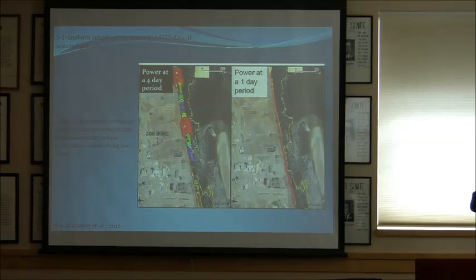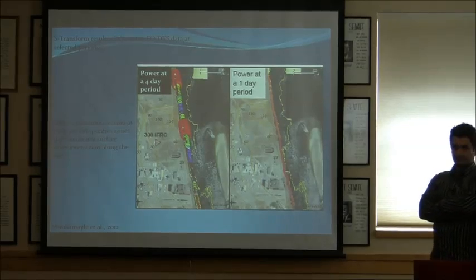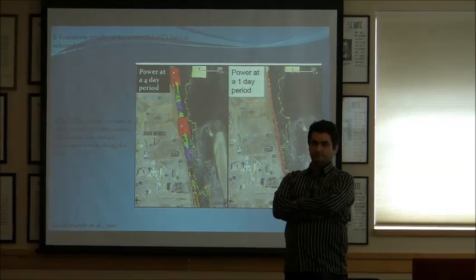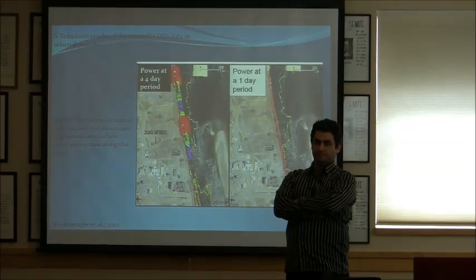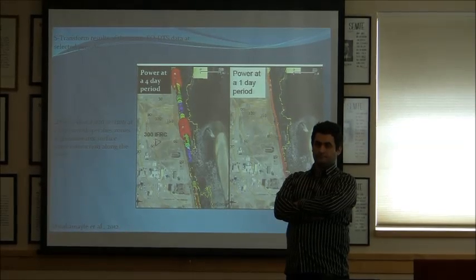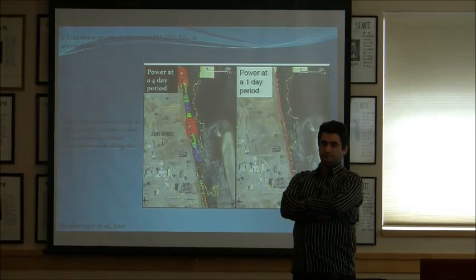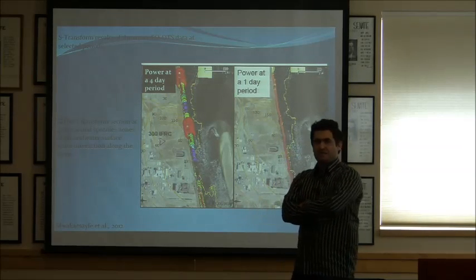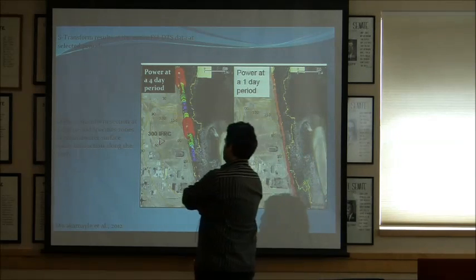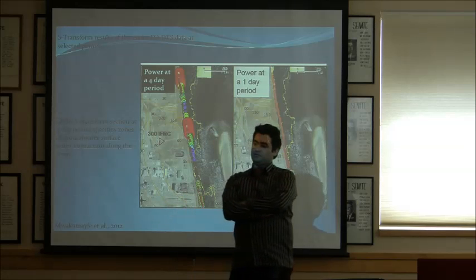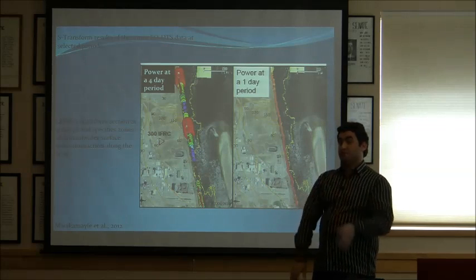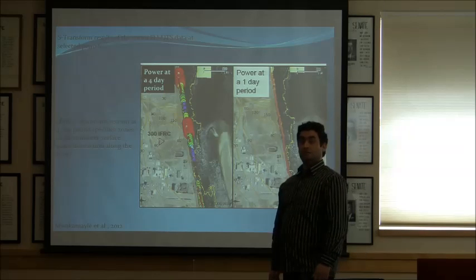I do have a question from earlier, when you were talking about resistivity and GPR. You said that it's good if you've got highly resistive materials, but that clays are particularly problematic. In case you have clay, there are tools you can measure along with resistivity, such as induced polarization.